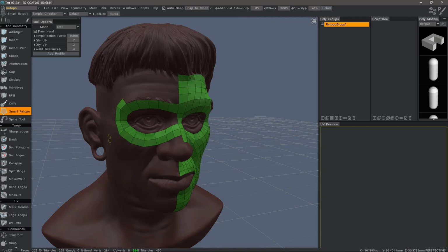You can actually create geometry out in the open on your voxel object, or you can use it to connect an already existing mesh with new geometry. For example, as I showed previously in the Strip Mode, you can click the first vertex, the second vertex, and 3D Coat will automatically create a spline along that row of edges, and it will automatically recognize the vertices. So now I can click and drag to create my second spline, and you can see how it snapped to that vertex, and it automatically connected those lines.